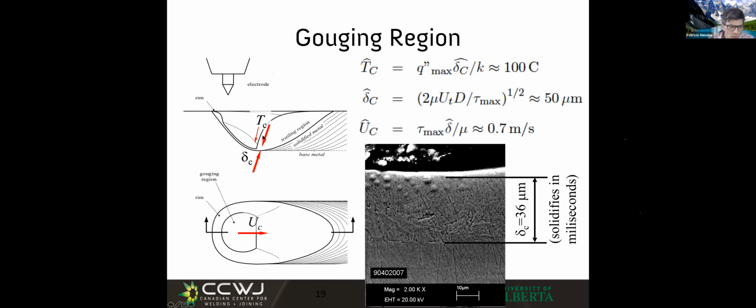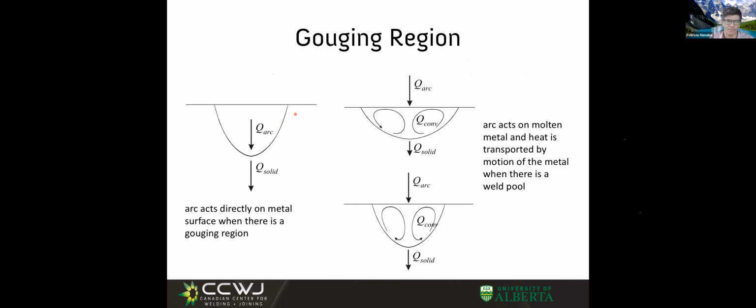And what we see here is that the heat of the arc will be digging pretty much directly into the metal, going for penetration, and the pressure of the arc is pushing back this other part, the trailing region. So very different than the mechanism of recirculating flows. We have the heat on the surface, and then all this is the molten pool, and we have recirculating flows. But in the gouging region, the heat of the arc goes straight into the bottom. This part is all hollow.